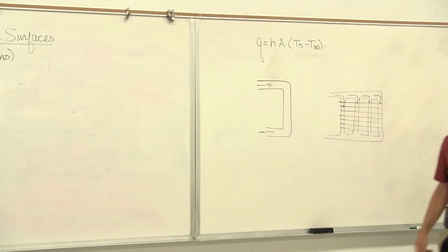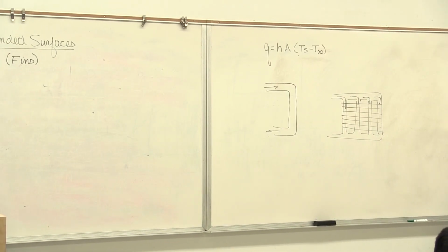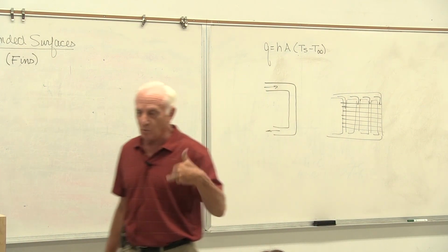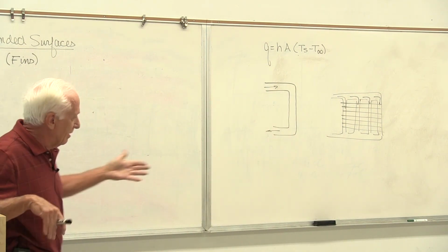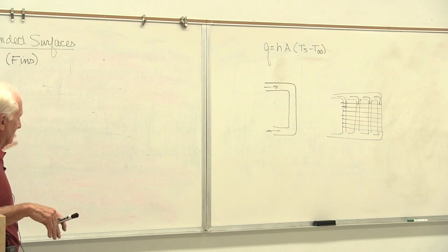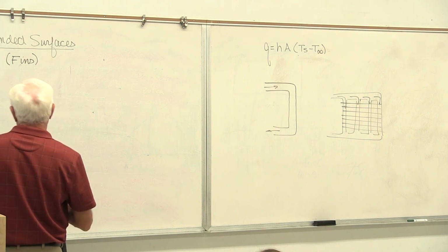Now the problem is, of course, when you add more fins and you add more tubes, you increase the weight, you increase the volume in the car that the thing takes up. So yeah, there's some play off there between the extra weight of the car, the volume it takes, the cost, and that's why, you know, we get paid the big bucks to try and optimize the heat loss from that particular engine.